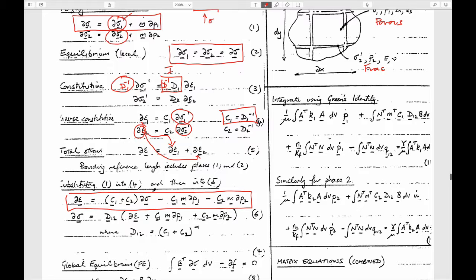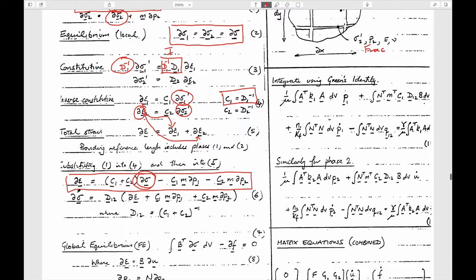But then these are the total stresses, which remember we want to solve our system of equations in. If we can now rearrange this equation so that it defines it in terms of this total stress, with all the other terms on the right-hand side, then we get equation 6, which is what we want. So before, what we had for single porosity, we had the fact that the total stress is equal to the effective stress plus a change in fluid pressure.